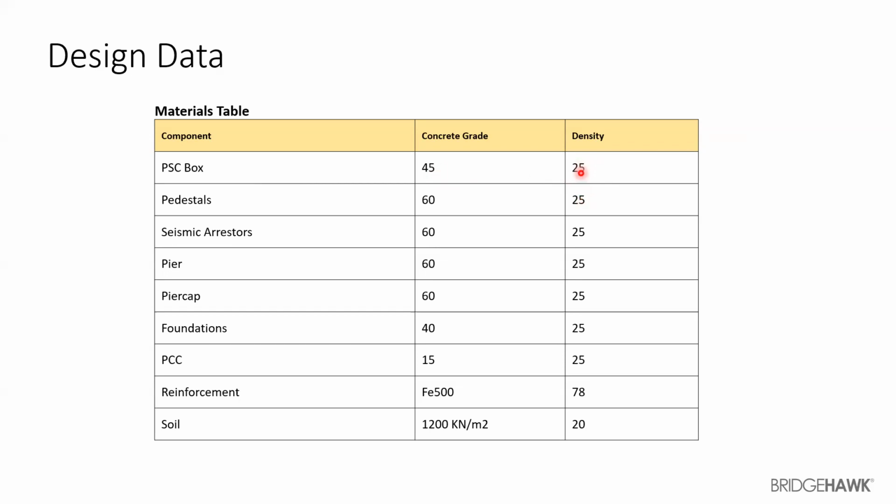So maybe in the DBR, they will say, okay, just take 26, take 24, whatever. They might change it a bit. Or they might also specify, okay, for PSC box, you have to use M30. So the DBR has to specify this. If not, then the detailed designer, in his own capacity, has to suggest it. And after a discussion and approval from him, they can reach on what sort of values he can take. So the pedestals are the ones over here.